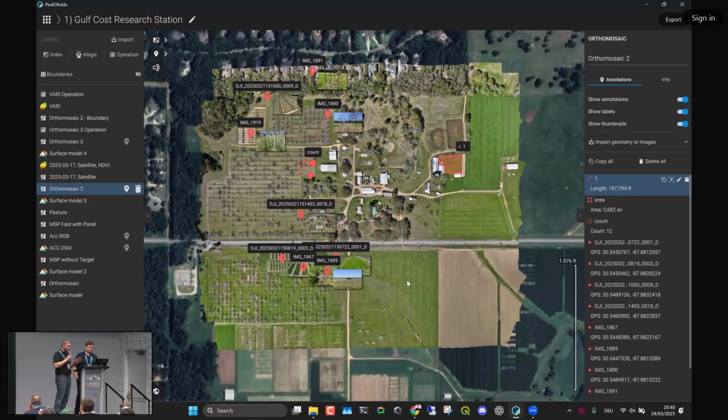That's actually pretty loaded, because it just depends on the surveying system. If it's a different datum completely, you could be in a whole different world. I mean, literally, projection can put you 10 feet off or something like that, or worse. And I don't normally see that. Normally, they're all using NAD 83 for their projections. Again, this is kind of mumbo jumbo if you're not really in the surveying world. But that's why I just encourage, very simply, if you just use the same source, you're probably going to be okay, with a few caveats. But for the most part, use the same source, you're going to be fine. If you're using two different sources, you need to figure out what their coordinate system is. That would help you. Yes?